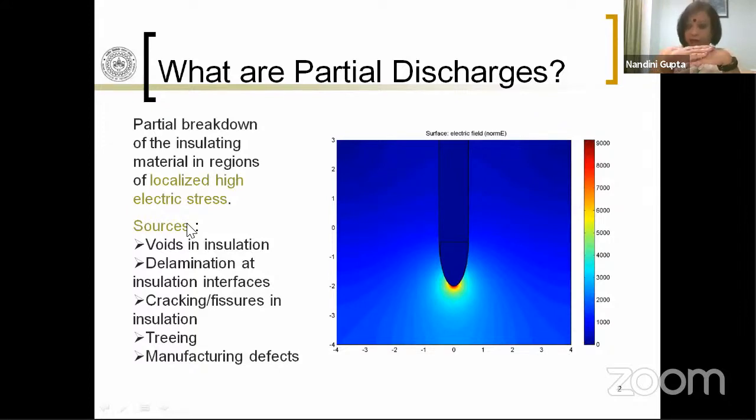If that does not happen, I would like to mention that when you have two layers of dielectric side by side and they have different permittivities, I'm not going to work it out for you here, but the material with lower permittivity will be very highly stressed. It will be more highly stressed because of the presence of the high permittivity material than if it was there alone.